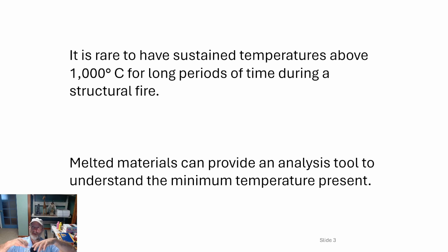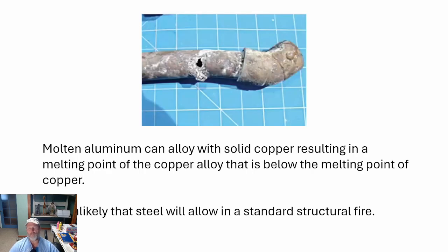But when you have a reflection from multiple sources, let's say a room's on fire, you're not only going to feel the temperature of that flame, you're going to feel this heat flux from other sources that raises up that temperature. And that's the kind of situation you're going to have in a flashover. So that's why, even though you have a rule of thumb of about 1,000 degrees Celsius, you can see higher temperatures. And reconstructing a fire, you're going to use temperature in some cases in terms of deformation as well as what material melted and what didn't, and reconstructing how that fire progressed and what it might have looked like.